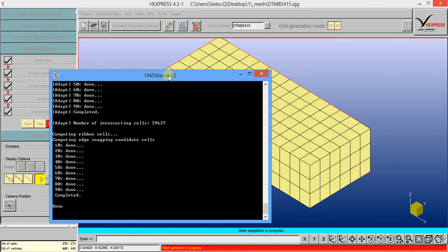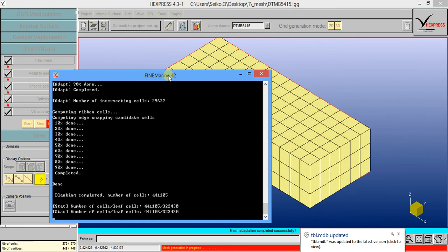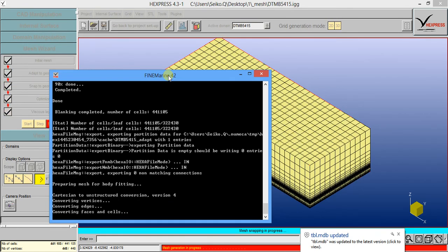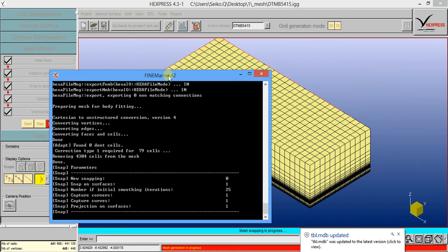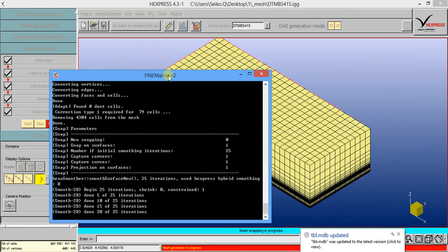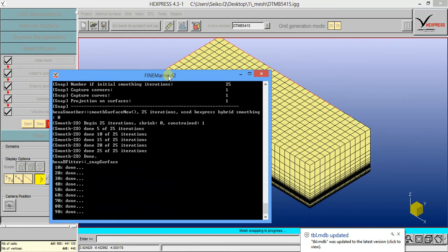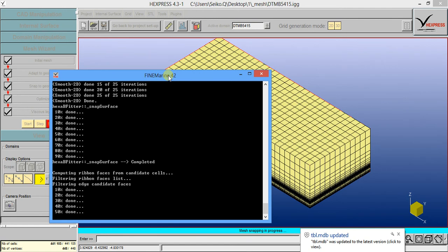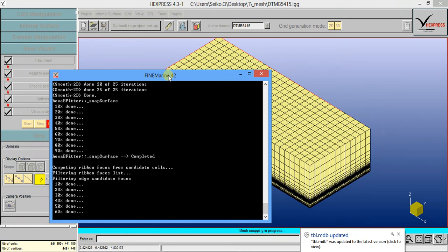the wizard. Remember that if you create a depth of 1 meter, you create a different set of mesh properties. If you define 2 meter depth, 5 meter depth, each of them will have its own set of mesh properties. Likewise, if you create a wave, and let's say you put 0.1 meters as an amplitude, it will have different mesh properties as well.